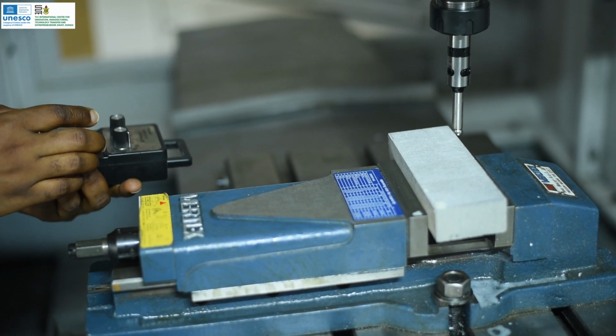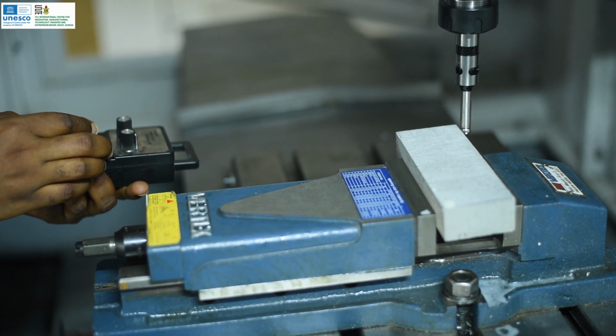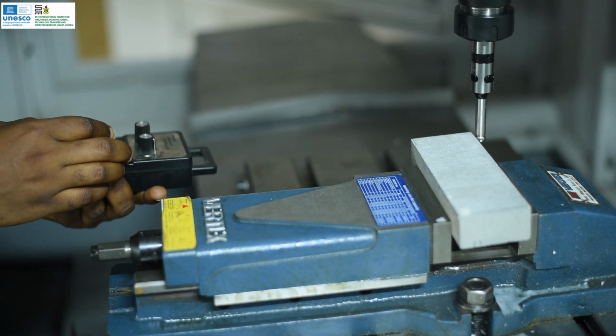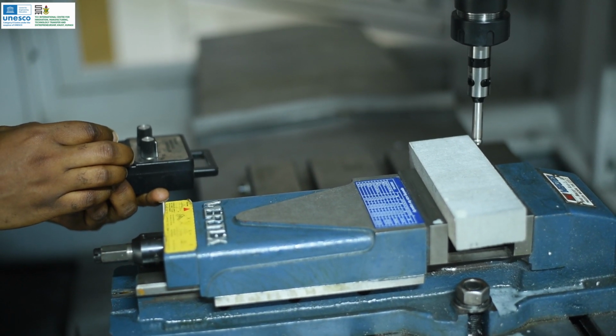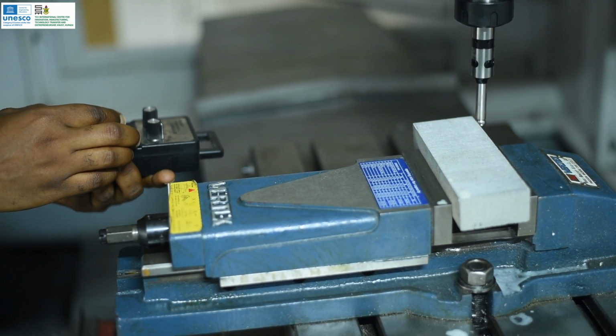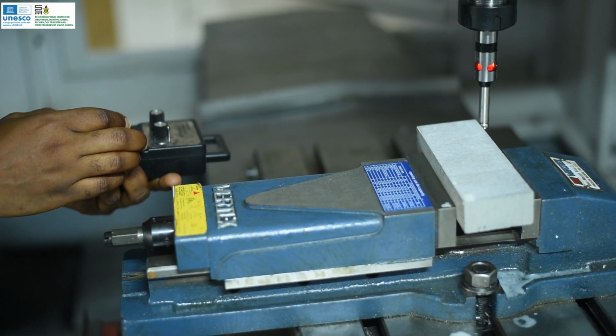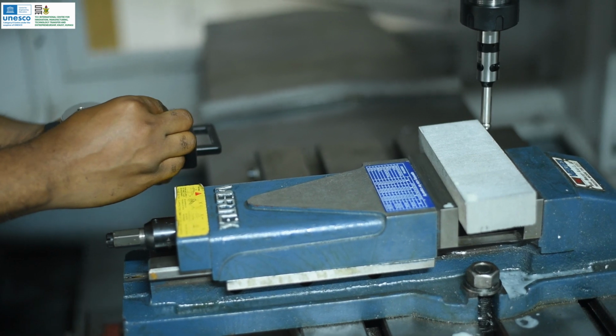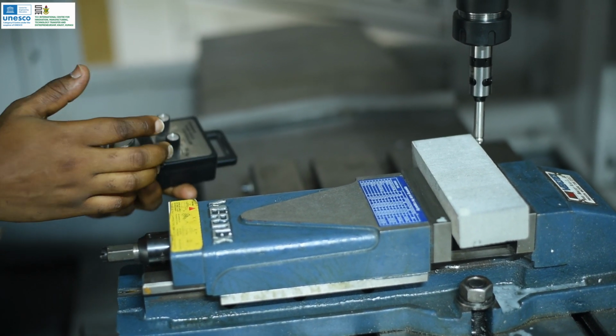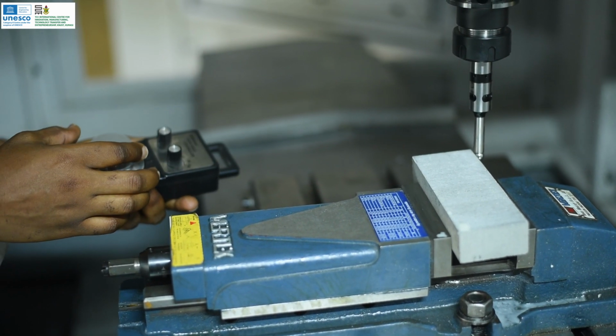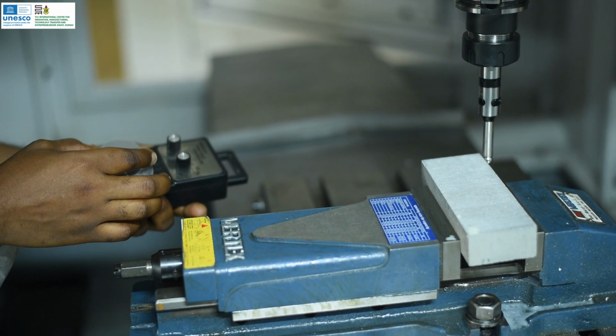It's important not to crash your workpiece into your edge finder. So we'll move as slowly as possible, just so that we barely touch the edge finder, and then we can move to the finest X1, and then jog again.